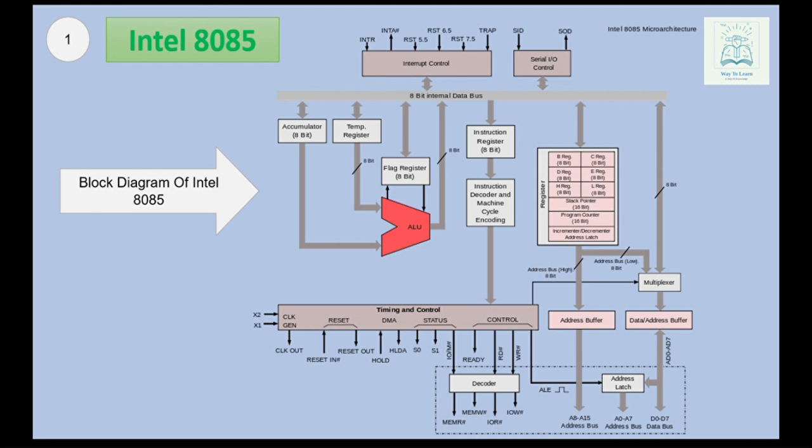This microprocessor consists of 40 pins as well as works with 5V power supply. This processor can work at a maximum frequency of 3 MHz. This processor is available in three versions such as 8085AH, 8085AH1 and 8085AH2. It has 80 basic instructions and 246 opcodes.